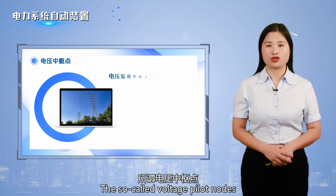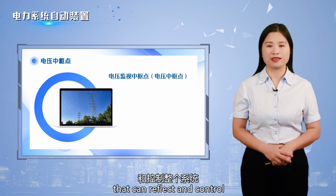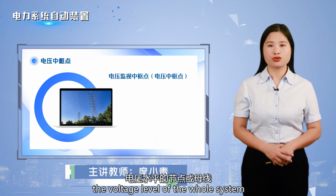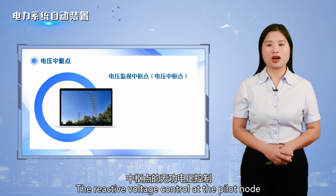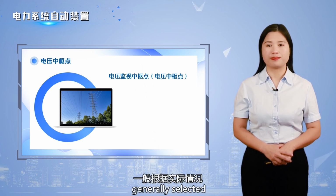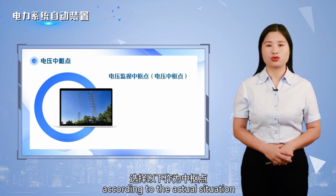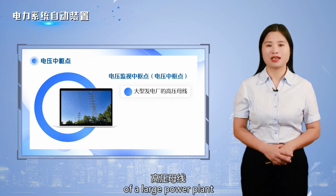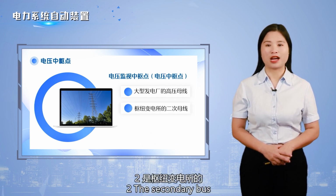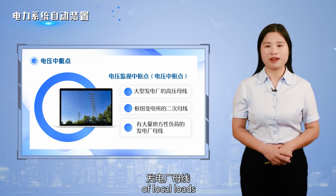The so-called voltage pilot nodes are those nodes or buses that can reflect and control the voltage level of the whole system. The reactive voltage control at the pilot node is crucial, and the following are generally selected as pilot nodes according to the actual situation. 1. The high voltage bus of a large power plant. 2. The secondary bus of a hub substation. 3. The bus bar of a power plant with a large number of local loads.